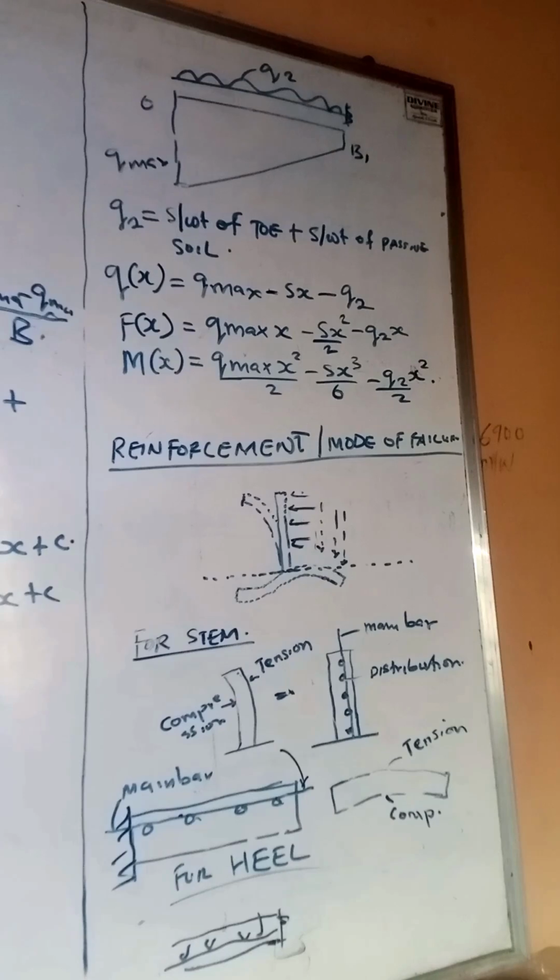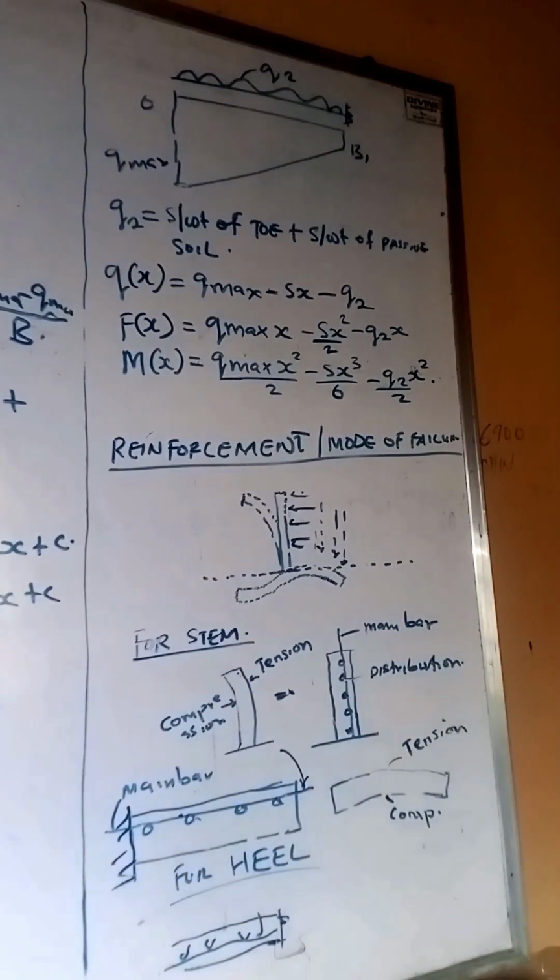Also take note, to obtain the moment due to the stem, all you need to do is integrate the pressure function of the stem. Once you integrate that for shear and also for moment, you have the moment expression.